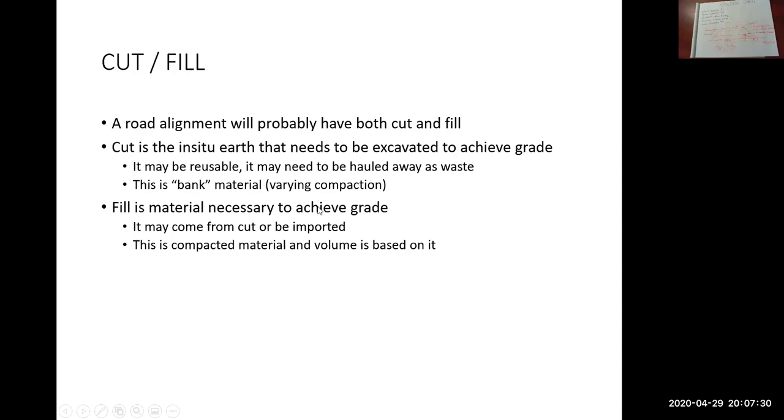So every time you place fill, whether it's embankment fill, subbase gravel, base gravels, it always has to be compacted. I guess I should clarify, that's in a traveled roadway.